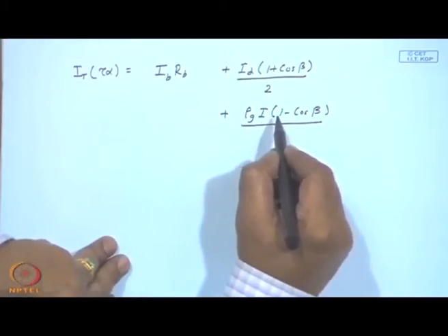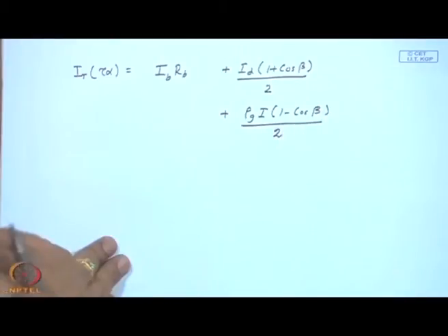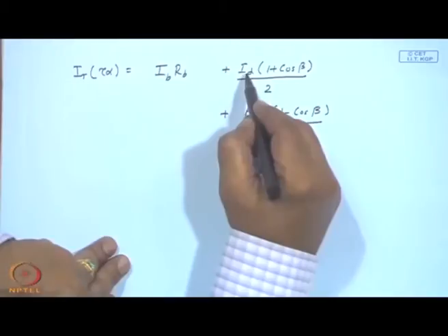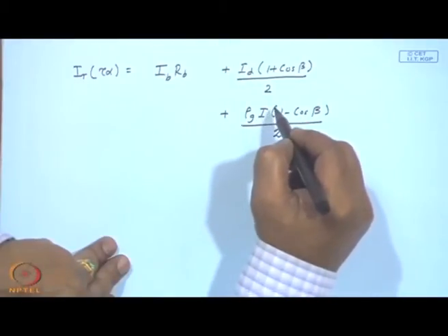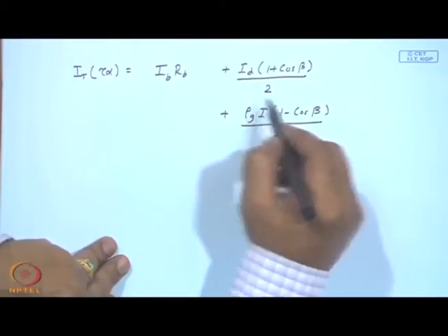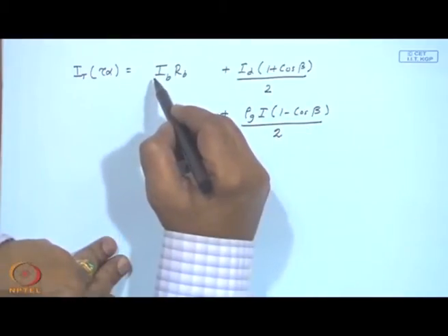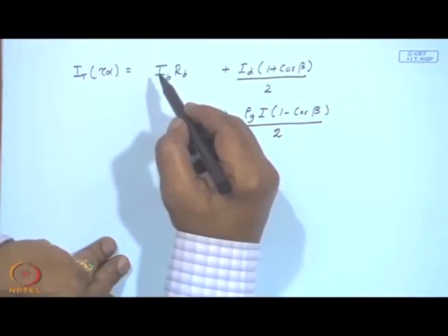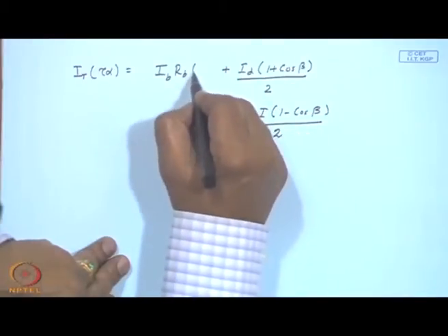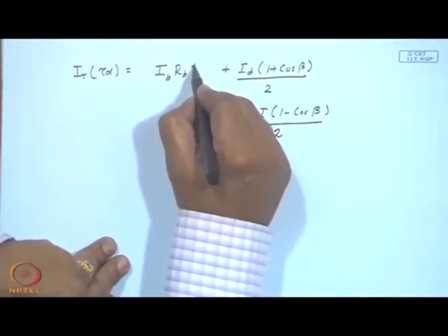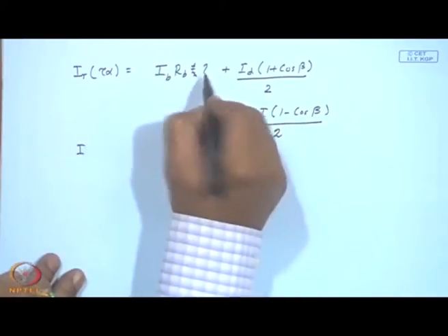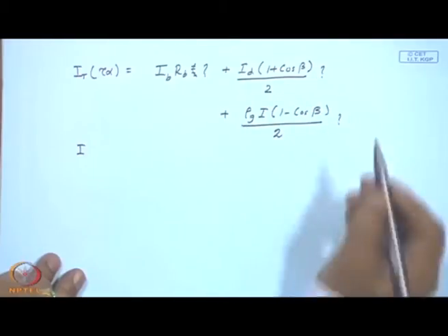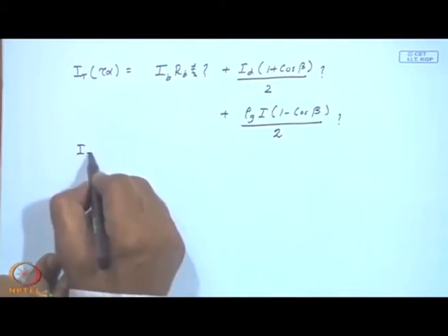which will appear in many orientations. However, even if we assume it to be isotropic, the effective angles at which the sky diffuse and the ground reflected radiation fall are a priori not known, though the direct radiation will occur at our theta, the angle of incidence. So, I shall associate each term with the corresponding transmittance absorptance products.